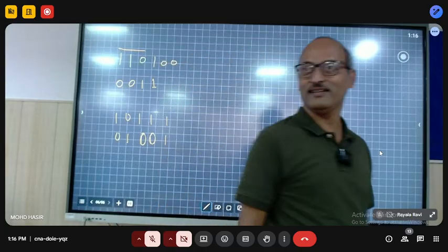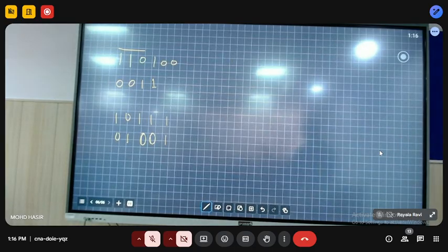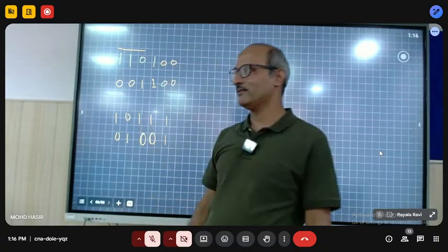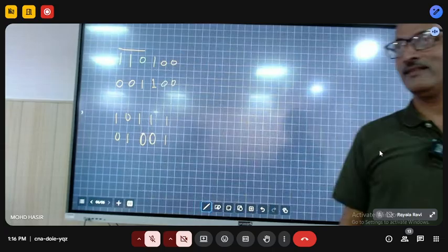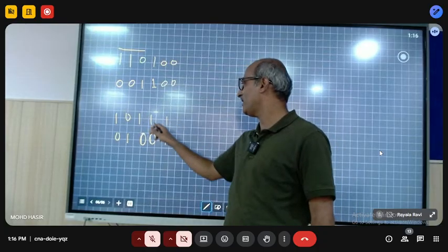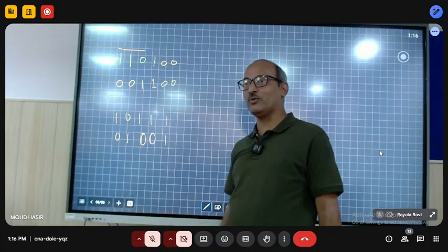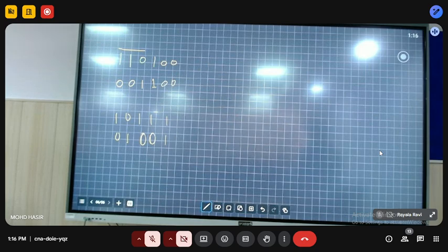दूसरा एल्गोरिथम क्या बोलता है? टूज कॉम्प्लीमेंट, दूसरा एल्गोरिथम। Start from LSB, find out the first non-zero bit. Okay, so up to that, write the number as it is, and the rest of the bits should be complemented. Right? That is the second algorithm. I am interested in implementing this. I don't want that rote solution.